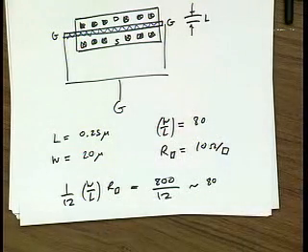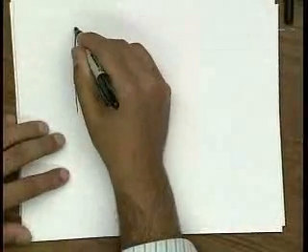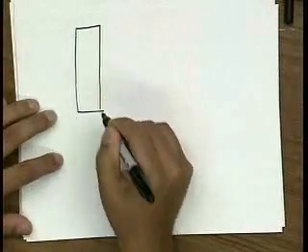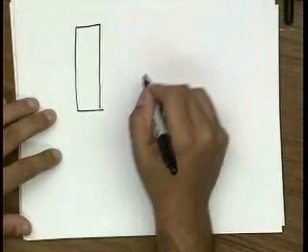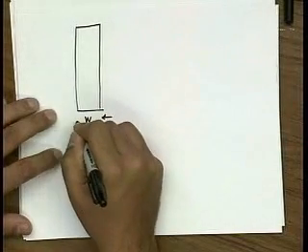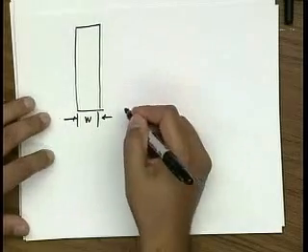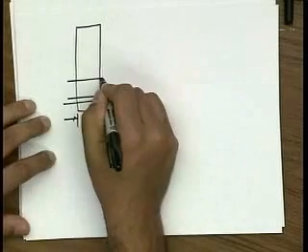In the back? Didn't you mention before multiple fingers would help gate resistance? Yeah, we play the same trick that we played with bipolar. We basically lay out our device as a multi-finger device. So instead of using a wide W, I can use a short W. And then I have basically many transistors in parallel.